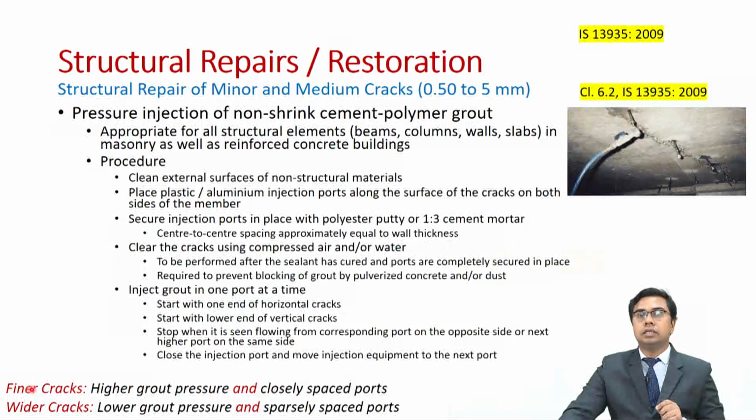Now, if your cracks are very fine, then you will require a higher grout pressure and closely spaced ports. If your cracks are wide, then you shall require lower grout pressure and sparsely spaced ports.